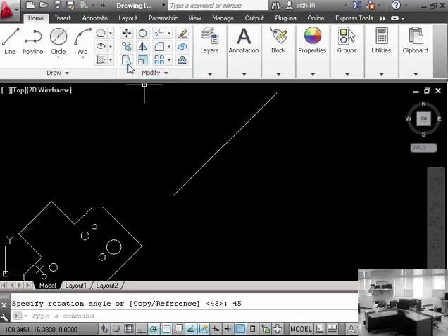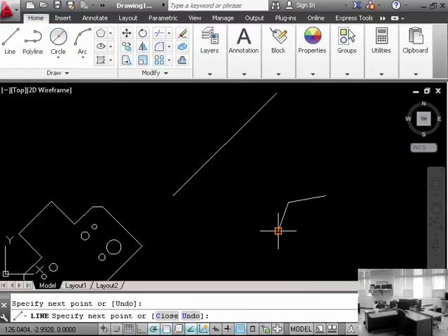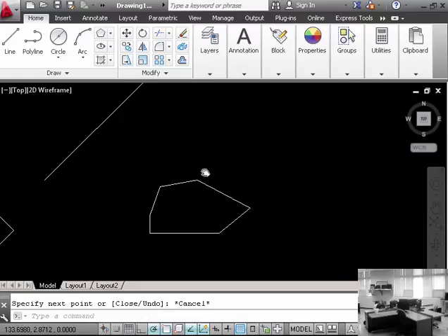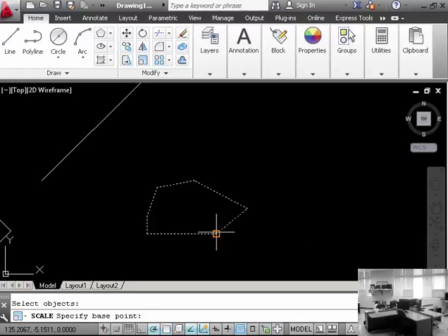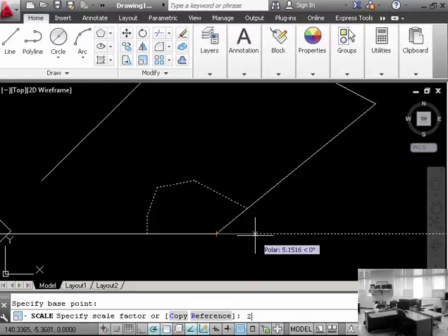You also have this great feature called scale. I'll show it to you real fast. We use this a lot of times when we scale imagery and parts for reproductions. You can use the scale tool to select objects. You're going to see the pattern of most of these tools on Modify involve selecting something, hit enter, and then you say base point, I want to scale it up by a factor of 2. Bam, there it is.